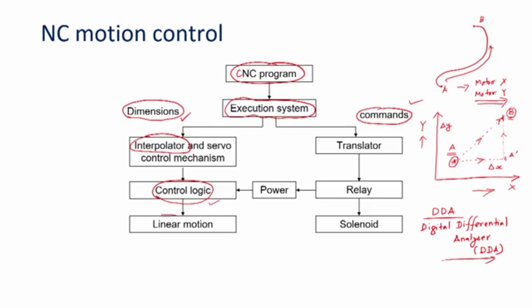Further, as far as the commands are concerned, these commands are to be translated and given to the relays, and relays are operating the solenoids. The solenoids are electromechanical actuation systems. We are providing the electrical signals and those electrical signals are converted into the mechanical switching operation.